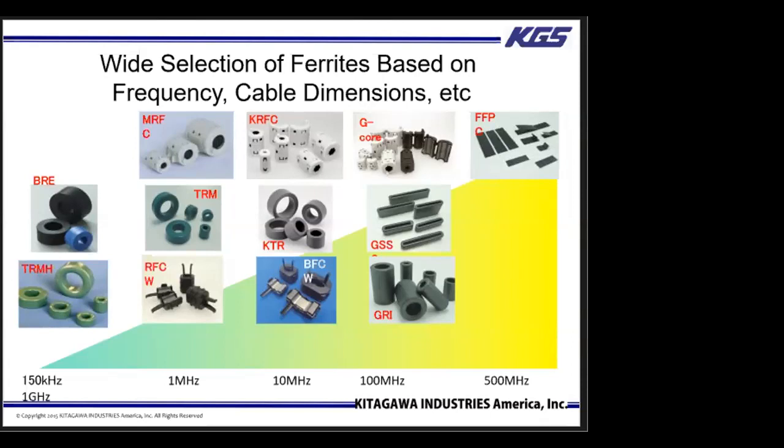In terms of saturation, I guess overheating is a symptom of saturation. So if you do see it happening, you just want to make sure that saturation is not occurring. It tends to happen more with normal mode filtering, so it's not as much of a concern for common mode noise filtering. Just an FYI on that side.